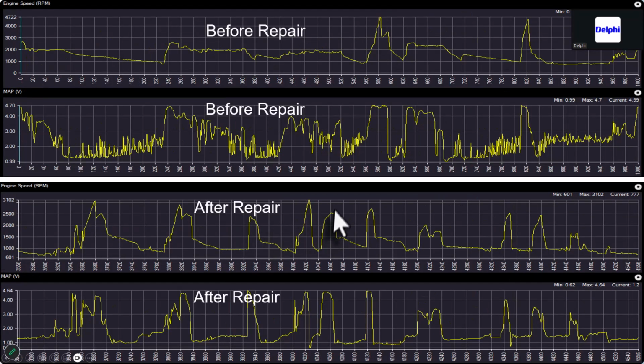So I'm running this by my good buddy, and we're talking about this. We're thinking, geez, on deceleration, where could I have that kind of manifold pressure change? The car runs great. Lo and behold, what we came up with, we told him from 2,000 miles away to put a PCV valve in this car. And he did, and look at the pattern on the bottom.